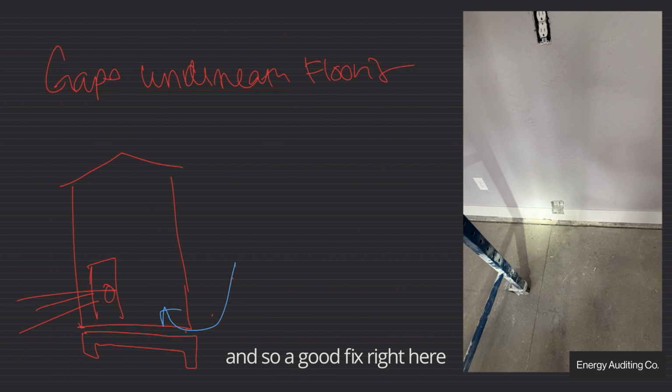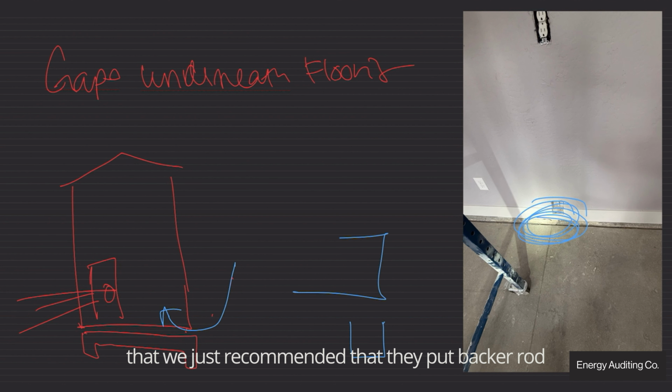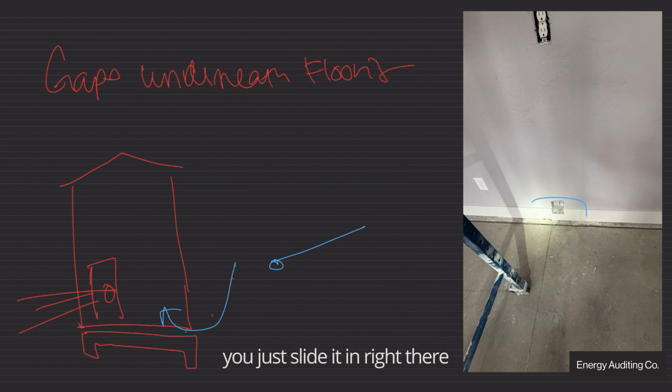A good fix right here, you can try the expansive foam route. You can also try caulking. We did a house one time, and this is the gap I'm referring to right there, where the gap was so large between those two materials that we recommended they put backer rod right in there. Backer rod is basically a tube. You just slide it in right there, stuff it in, and caulk on top of that.